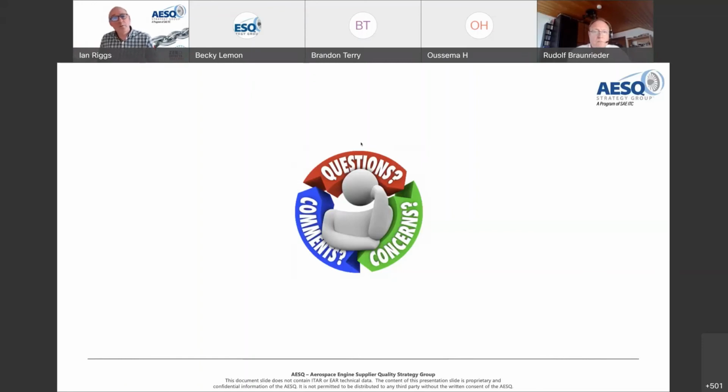But one of the things with FMEAs is, if you do an FMEA and you don't end up changing anything, you probably haven't done a very good FMEA. These are the sorts of questions that I think a lot of us find when we do an FMEA. Is our inspection good enough? Have we mistake-proofed everything we could mistake-proof? Did we understand what the severity was? And if we did, would we actually change how we make it, how we inspect it as a result of that?